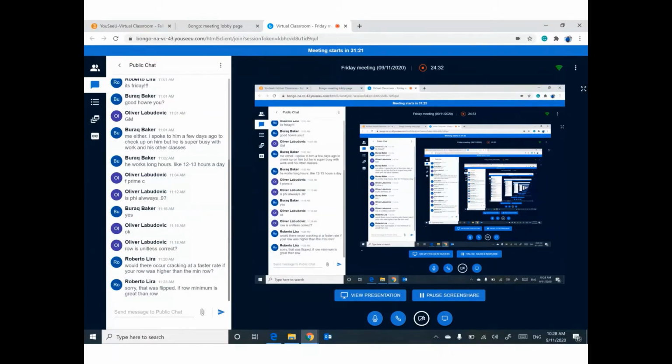minimum reinforcement is related to ductility, cracking, but in a different term, which is called ductility. Ductility means you have to keep cracking within the limit. You have to keep deflection within the limit. You have to keep the actual behavior of the beam within the limit. It's not accepted to see a reinforced concrete beam deflected too much, or a beam with cracks which are visible to you.